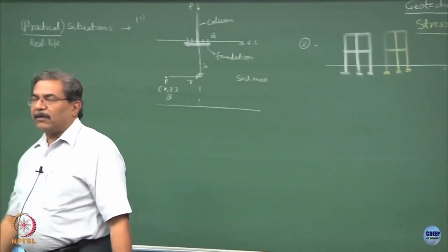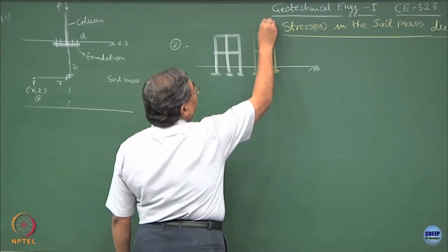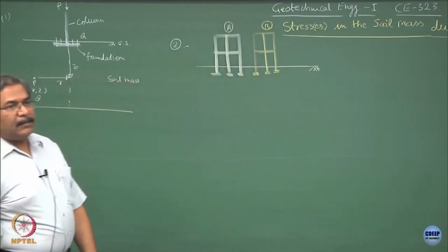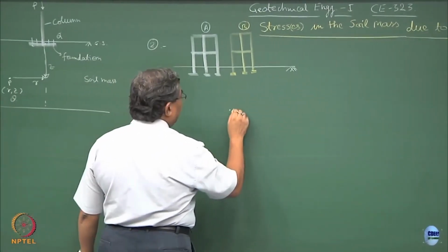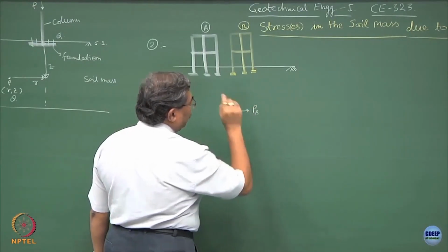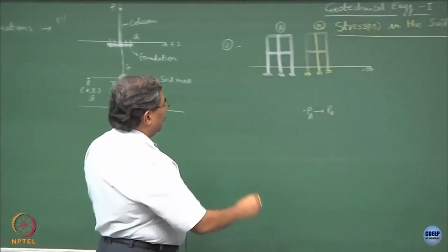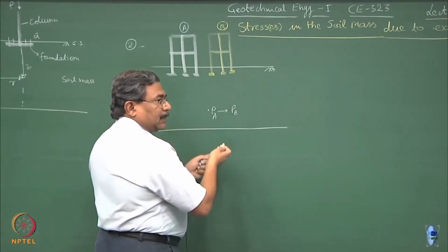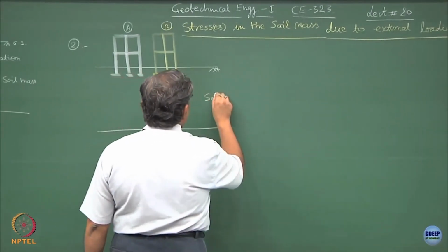So this is the building which is sitting on the foundation system. Now because of construction of building B, if the building A was already existing, what has happened? The state of stress at a given point P, which I have taken over there, has changed. So, PA has changed to PB, alright, and I would like to understand whether this system soil is capable of taking this type of loads or not, alright. So, this is again the soil mass.